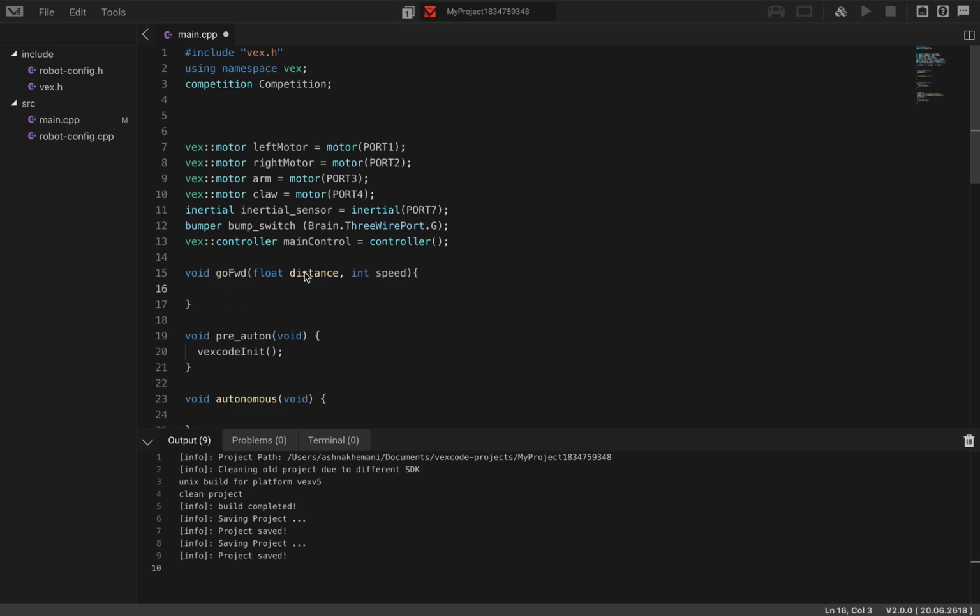So you can think of the distance as the number of revolutions or complete number of degrees that your wheels have to turn. And this really translates to that the number of revolutions your wheel turns is the full distance that it needs to go divided by its circumference, or the distance around the wheel. So you can look up circumference if you don't know what it is. I'm not going to explain it right now. But it's basically just the distance around the wheel.